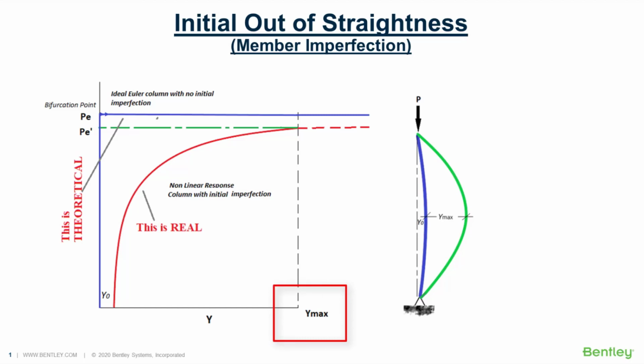So after limiting the maximum allowable displacement, the corresponding allowable buckling load can be projected and calibrated, which is less than the Euler load by some factor. And AISC, after a series of rigorous testing by several great structural engineers over the decades, calibrated the allowable buckling load limit for a column with an initial out of straightness of about L over 1470.